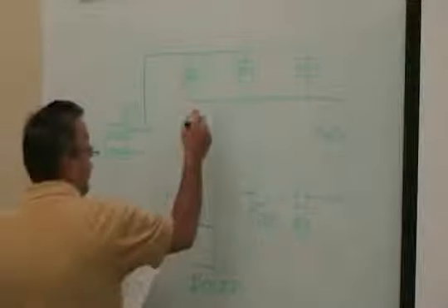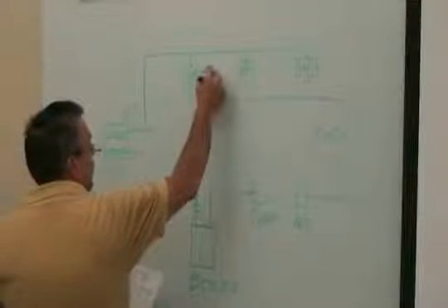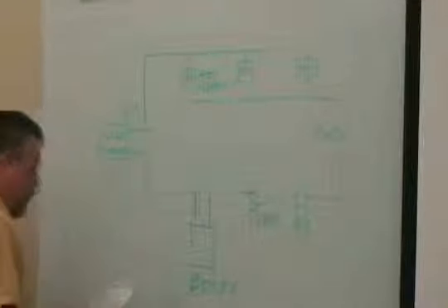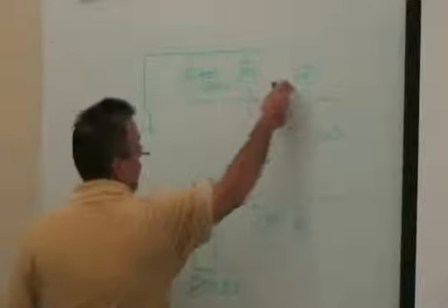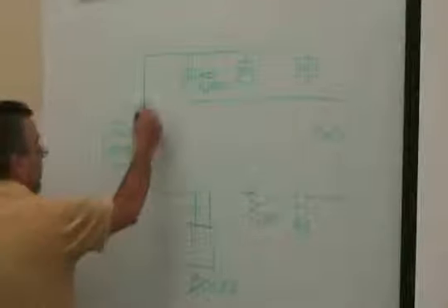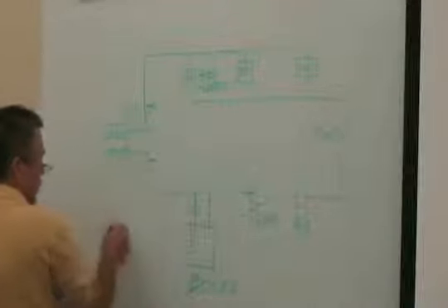Someone was asking about the temperatures. I can select a heat pump like this and probably produce 58-degree supply air right here in the cooling mode. And in the heating mode, and these systems, you know, this is a single pipe or two pipe system. You got a supply and return. Summertime, everything's cooling. I'm trying to maintain 90-degree water.